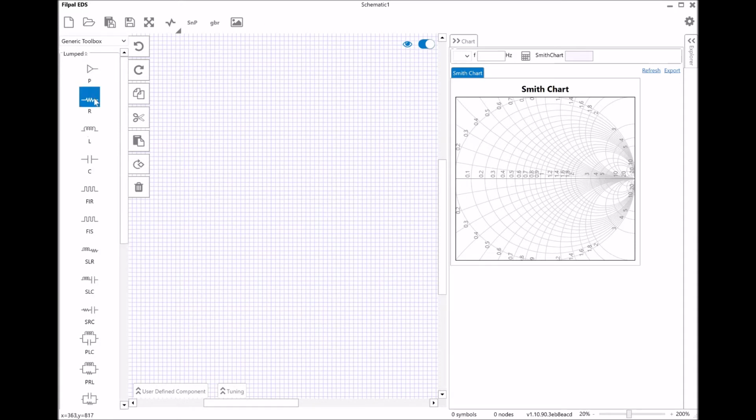Before I choose, perhaps I can guide you through a bit on what we learned in the previous video. So on this side is the short circuit end, this is the open circuit end, this is the inductive region, and this is the capacitive region. So I want to do one thing using this Smith chart, which is the impedance matching.